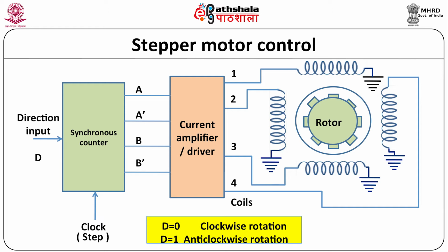A stepper motor is a motor that rotates in steps, typically 1.8 degrees per step, rather than a continuous motion. The magnetic coils or windings in the motor must be energized or de-energized in a particular sequence to produce a stepping action. Digital signals are normally used to control the current in each coil.